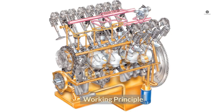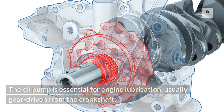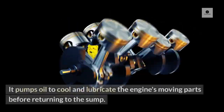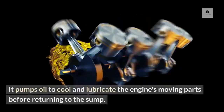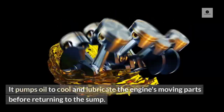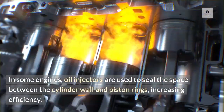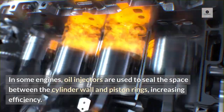Working principle. The oil pump is essential for engine lubrication, usually gear-driven from the crankshaft. It pumps oil to cool and lubricate the engine's moving parts before returning to the sump. In some engines, oil injectors are used to seal the space between the cylinder wall and piston rings, increasing efficiency.